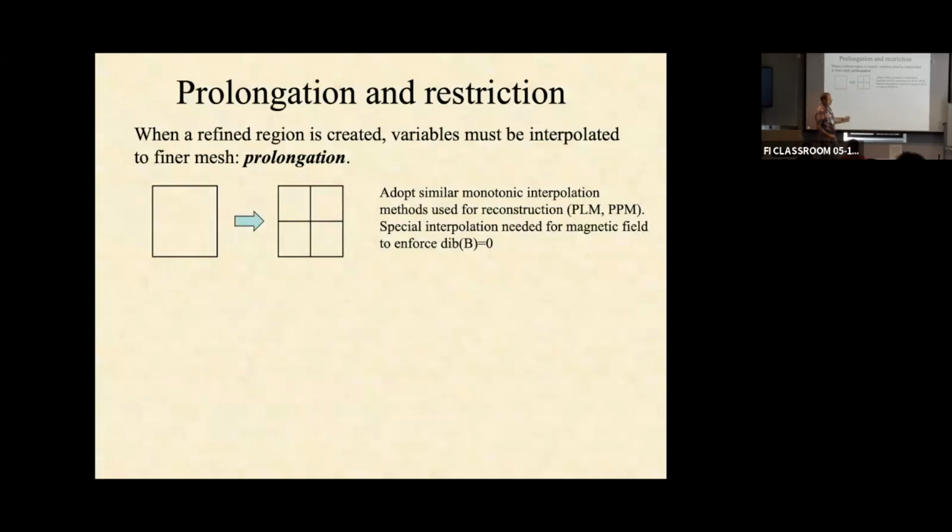In fact, it's sort of worse because I was going to use the board, but maybe I can just show it with my fingers. The cell center here is located there, and the cell centers for these cells are not at the same Y location as the cell center of your original mesh. So to get these cell centers, you automatically have to do a multidimensional interpolation. You need to interpolate a quarter of a grid cell away from the cell center left and right, and a quarter of a grid cell up and down, if you like, in 2D, and in 3D you need another one. So it's automatically a 3-dimensional interpolation that you need to do this prolongation step.